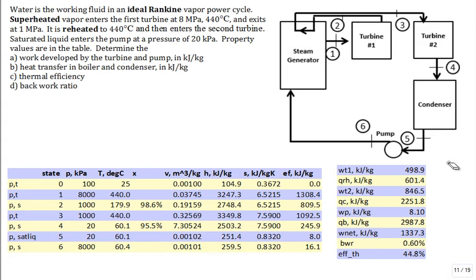Okay, so same strategy. Get a temperature, pressure column going. Get your enthalpies, your entropies. From that, fill it up, populate it. Know how you're working through the table. This is my little helpful reminder column. State 1 is determined by knowing temperature and pressure, state 2 by pressure and entropy, state 3 by pressure and temperature, etc.